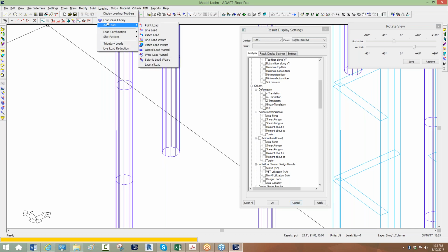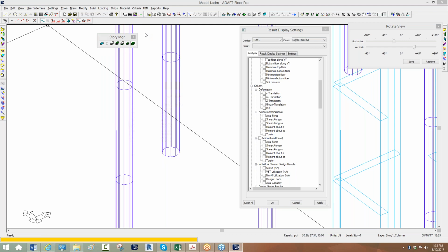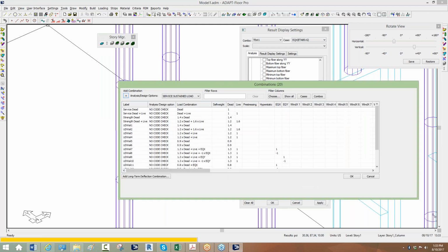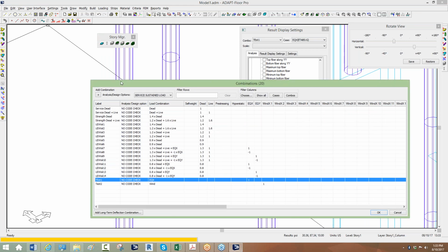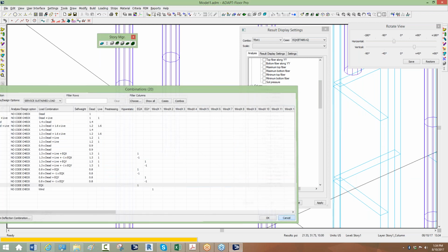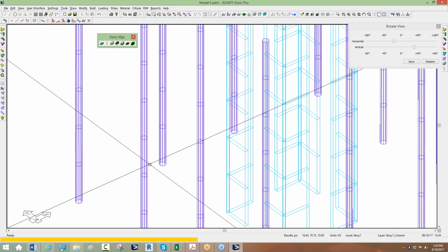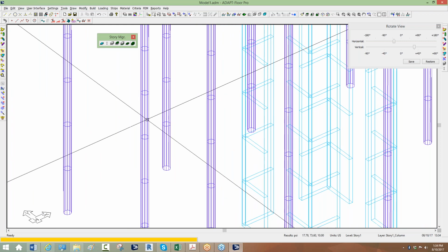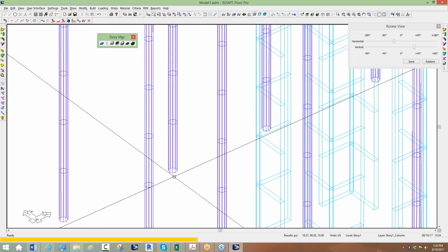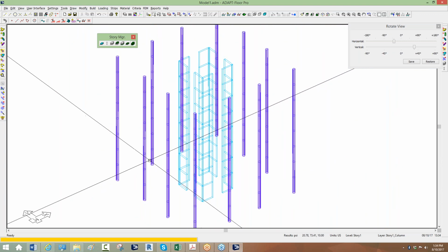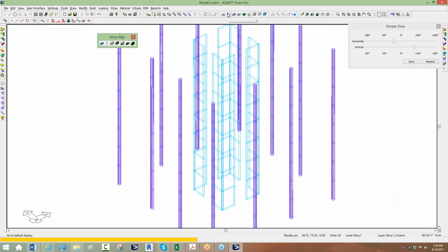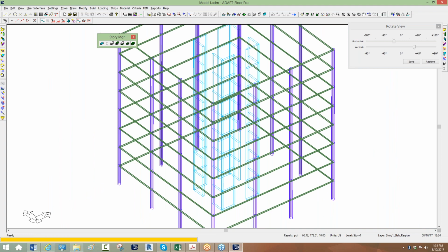Make sure I have the right combination in here. So we'll go to load combos, FEM, and test 1 was EQX. So the results should be pretty close, depending again on how the models were set up. I'm not exactly sure why those results are so dissimilar, but that's something we can look at on our end. But that just shows you the usage of the rerun of applied reactions, or applied forces rather, in Builder.